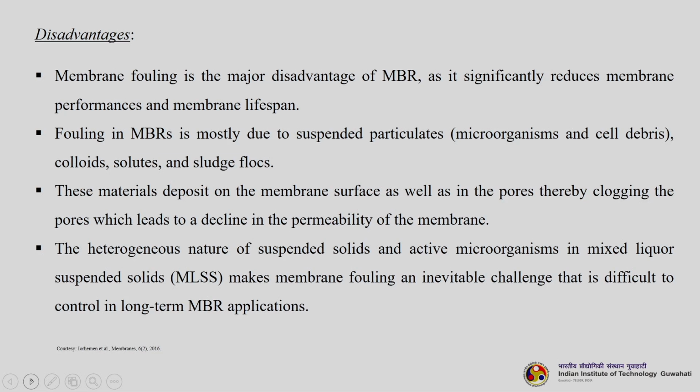So, the fouling of the membrane significantly reduces the membrane performance and membrane lifespan. Fouling is mostly due to the suspended particulates, which are microorganisms and cell debris, colloids, solutes and sludge flocs. These materials deposit on the membrane surface as well as in the pores, thereby clogging pores, which leads to a decline in the permeability of the membrane. The heterogeneous nature of suspended solids and active microorganisms in mixed liquor suspended solids, that is MLSS, makes membrane fouling an inevitable challenge that is difficult to control in long term MBR applications.